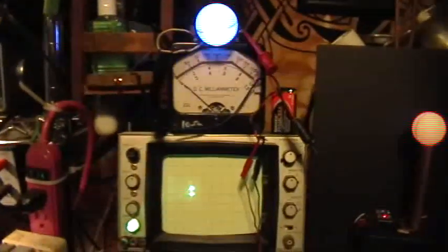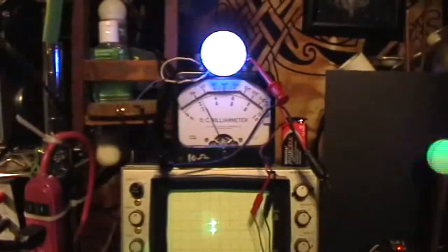Okay, so let me get a little bit of the light up there. Alright, so can you see what's going on so far? Don't pay any attention to this. So we've got positive and negative sine wave of 6 volts, and it's lighting the LED when it goes over about +3 volts and showing current flowing on the milliammeter, right?